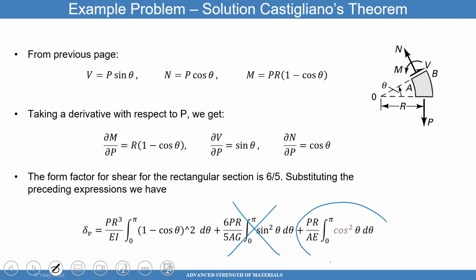But this term I want you to keep, because that term, you already learned what it is. That's the axial extension of that beam. And you know the formula for the axial extension already. We covered what that is. You don't have to calculate strain energy for tension load, right? Is that correct? We taught you what the formula was: P squared over 2EA or something like that? Remember that formula? Yes or no? You probably forgot now because we covered it a long time ago.